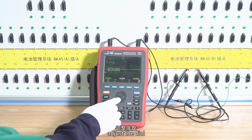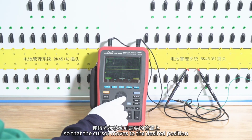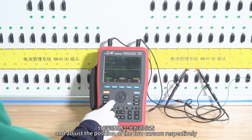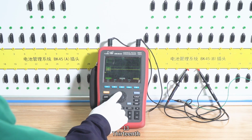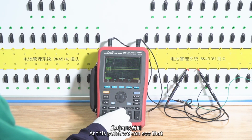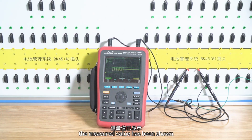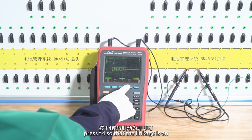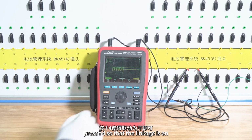12th, adjust the dial so that the cursor moves to the desired position, and adjust the position of the 2 cursors respectively. 13th, we can get the measurement value, V. At this point, we can see that the measured value is shown in the upper left of the display. If you want both cursors to move at the same time, press F4 so that the linkage is on.